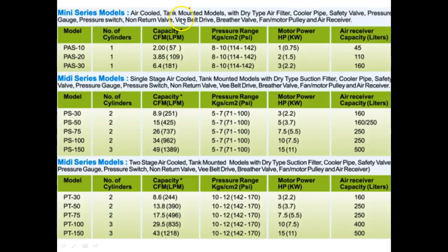This is another one, air-cooled, tank-mounted with dry air filter. By the way, another thing you got to do on your compressor is make sure you filter that input air, right? Because if you don't filter it, what's going to happen? Well, it's going to clog everything up. All of these little valves, these little check valves and everything's going to get clogged up. It's just like running your car or your lawnmower without the air filter. Get that trash into your cylinder. Your cylinder starts wearing out a lot faster. You start burning oil all the time because you let all this junk get into there. So filtering is very, very important.